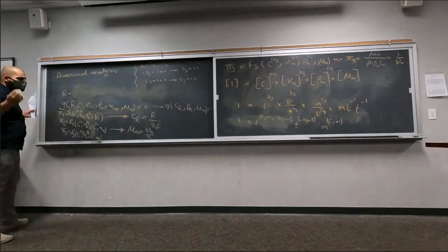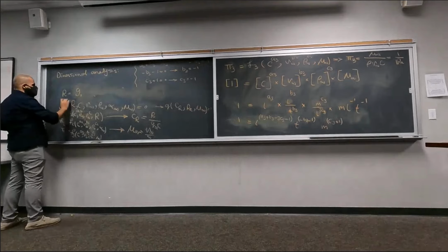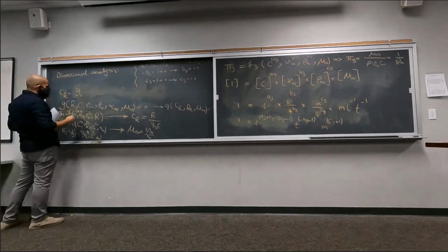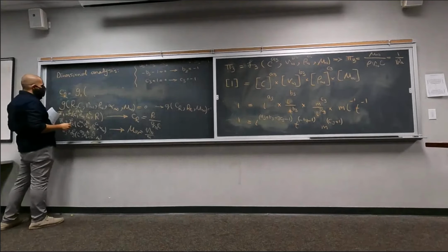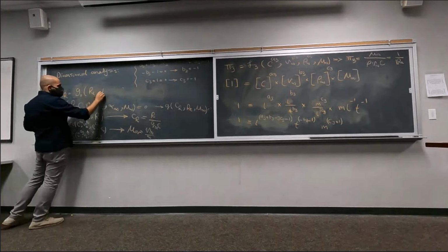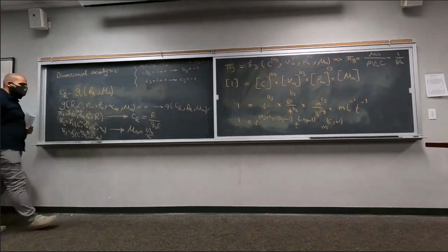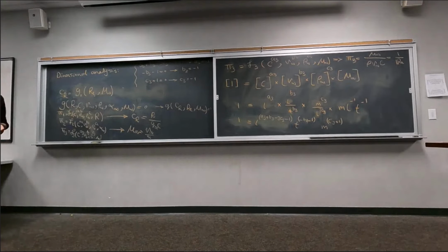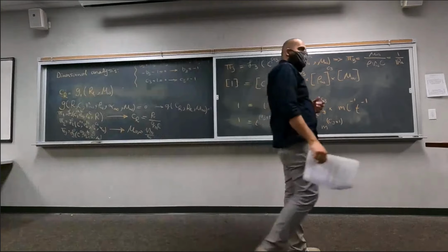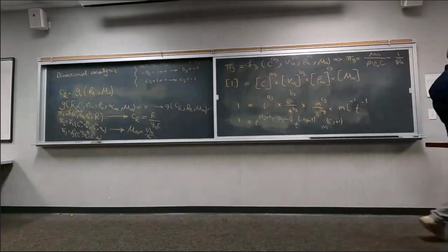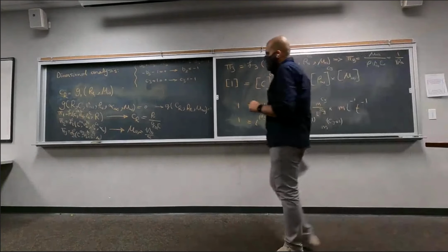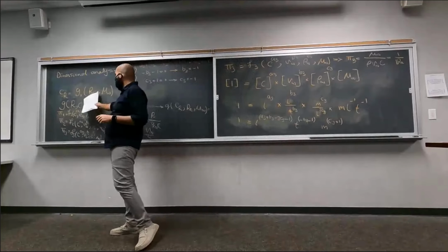Let's call it G1. Here C_R, we are dealing with the force coefficient, from now on, this analysis at least, is going to be a function of Reynolds number and the Mach number. So essentially, you should be able to characterize any type of flow over an airfoil with a constant angle of attack with only changing these 2 parameters.